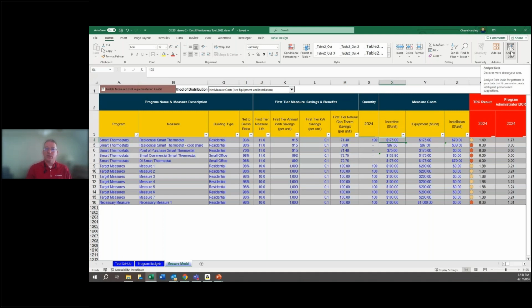But that is intended to represent the incremental cost, and that's a good call out because we don't want to fully burden the program, the costs for the program, the cost for the ratepayer. We don't want it to look like if you build a house, the whole cost of this house is burdened onto the energy efficiency program. That's not it at all. It's only the incremental cost of the efficient equipment, right? If we're paying an incentive on an air conditioner, we know that they were going to have an air conditioner one way or another. The baseline air conditioner is now a 15 SEER, and they're going to put in an 18 SEER. So the savings is basically 3 SEER, but that baseline piece of equipment cost $10,000 and the efficient one costs $13,000. We would put in the equipment cost field that incremental cost, $3,000, not the whole cost of the equipment. Hopefully that answers the question. That is what that is intended to represent, though.